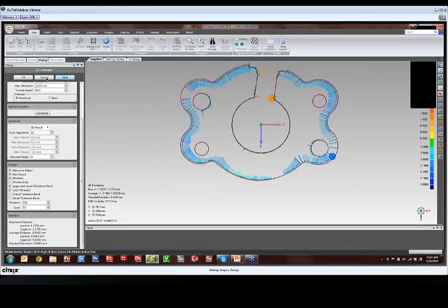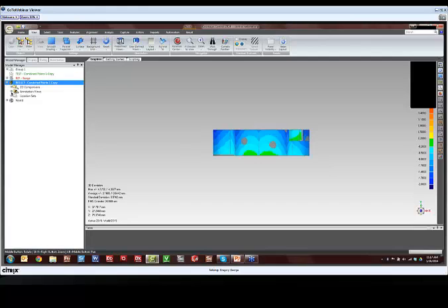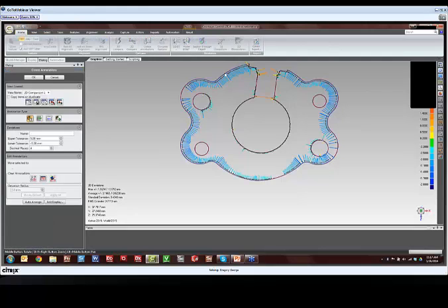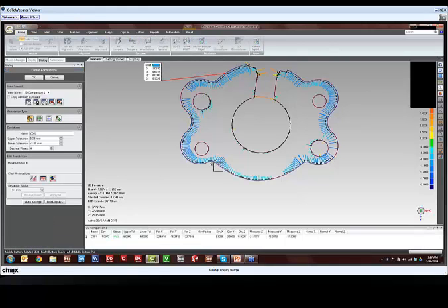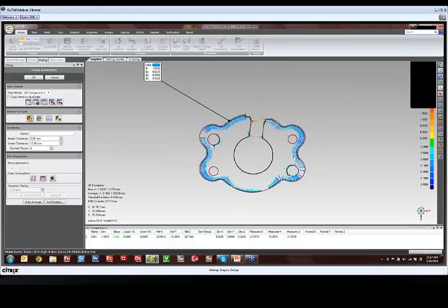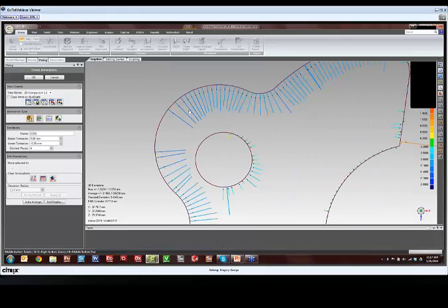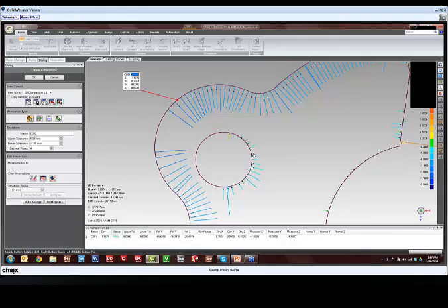If I want to annotate that, I can get out of this tool and come over to my 2D comparison and hit the annotations and do the same thing that I did in 3D compare, except with the 2D compare. And then the view format works the same as well. So if I come in and drag out these comparison points, I can save views. And if I say new view, I can come into a certain location and only pull annotations in that area as well. And then hit save. And again, just like before, the table is prepared below, and that's going to end up inside of the report.